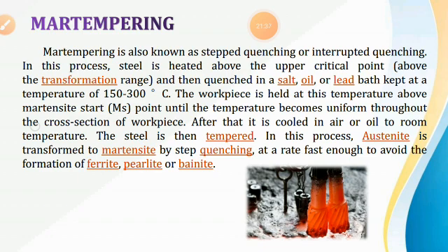In the case of martensite, the chromium steel contains 12 to 14% chromium and 0.12 to 0.35% carbon, and is called martensitic stainless steel. These steels can be easily welded and machined. These are austenite and martensite.